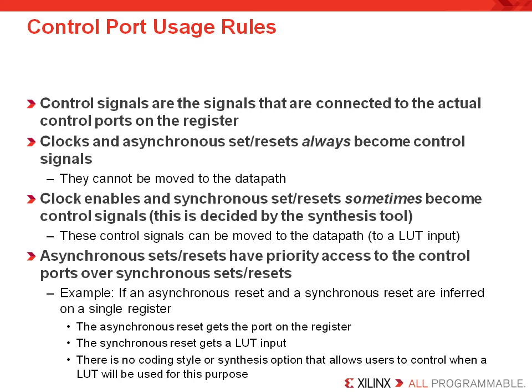An asynchronous set or reset port cannot be implemented as a LUT input, so your synthesis tool and the implementation tools don't have the ability to map this control signal to a LUT input. So it's one of those things that we would say, if you're building an asynchronous set or reset port, that you should carefully evaluate whether you actually need it or if you can instead code it as synchronous.